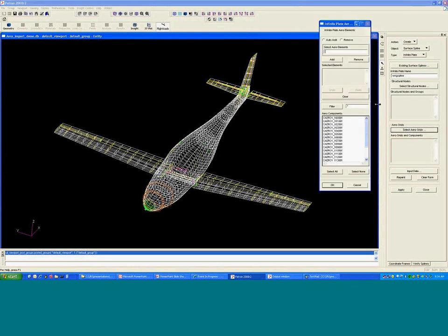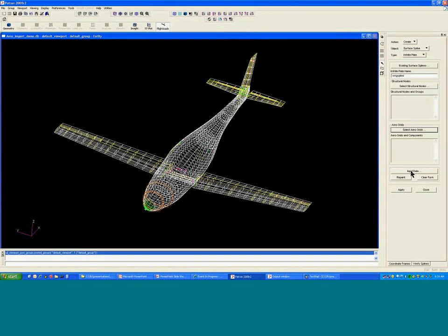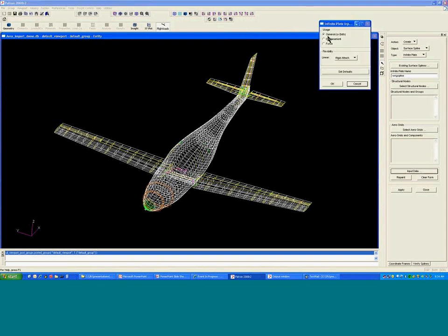And then on the aero mesh, you're going to apply that group of nodes to one or more aerodynamic panels. Essentially that's what you're doing with splining. If you create a spline with a group of nodes and a group of panels, you can then come in here to the input data and say whether that spline can be used for mapping forces or displacements or both, and whether you're going to put any flexibility in that. These are just little knobs on some of the splines.